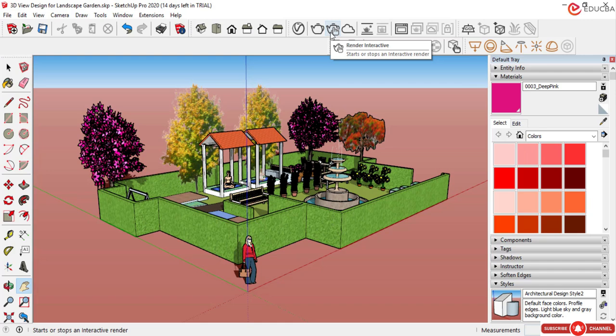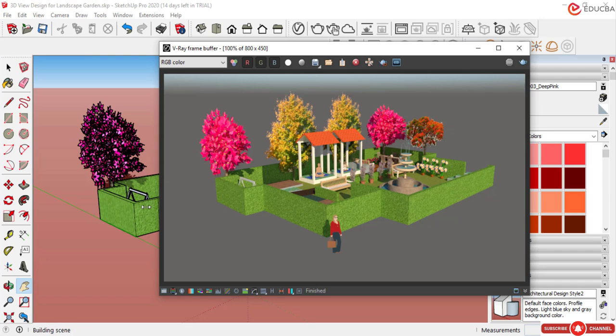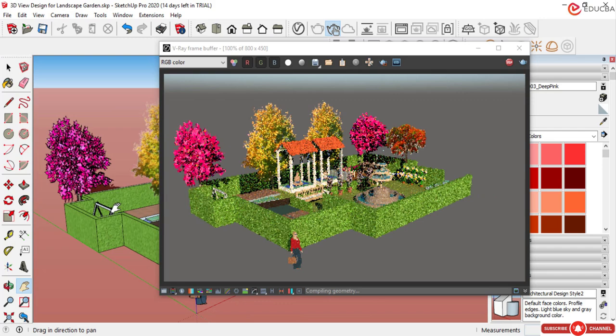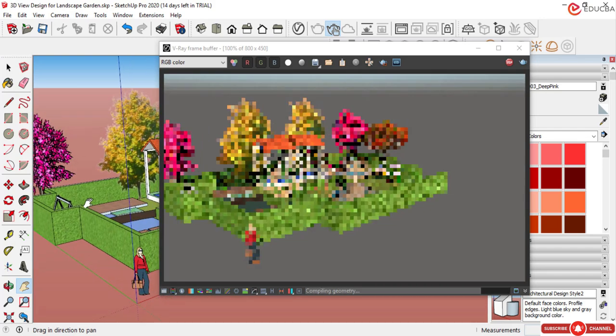So in this command, we can rotate the object in 3D or 3D orbit. We can run the command of 3D orbit by using this tool. If you want to see, click here, and again it looks like this, our image. And if I apply the pan command, it automatically changes inside the window.